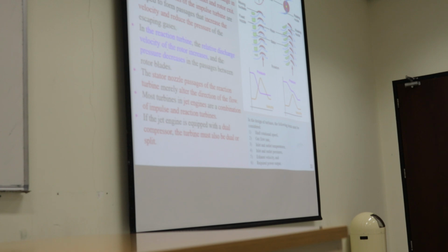If the pressure is decreasing here, why is the velocity not increasing as we have flow between the moving blades? Because of the impact also. The kinetic energy is converted to mechanical shaft work. It should increase, but the shaft is rotating. So in this case, the kinetic energy directly gives some impulse to the blade, and it will drive the shaft. In a jet engine, what kind of form should we have? Both. It should be a combination of both of these. We need to hit, and we need to have reaction also.